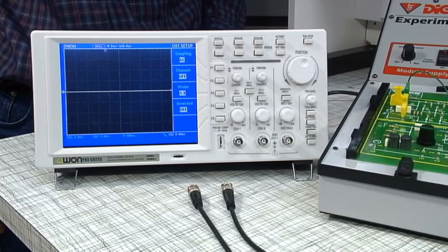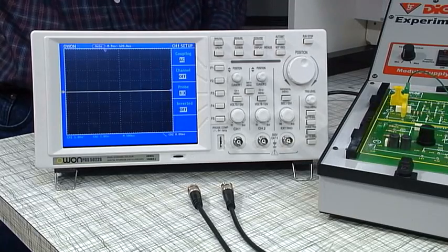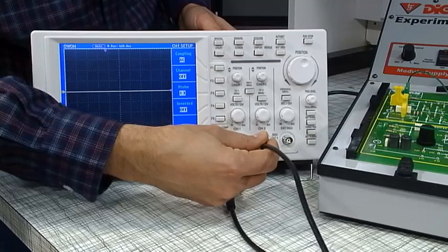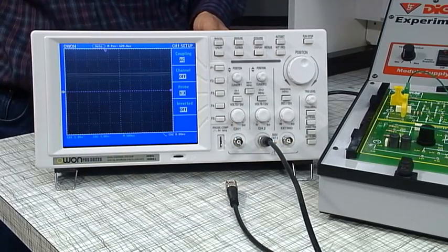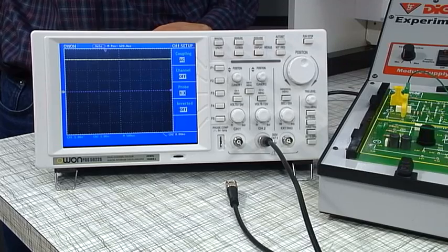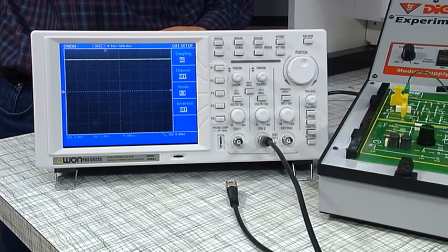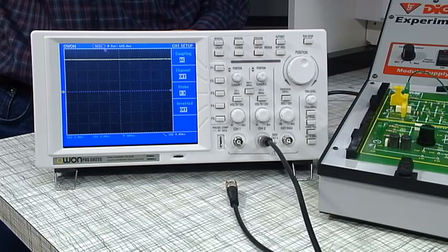Oscilloscopes can also be used to measure DC voltages. Unlike AC signals, a DC signal has no time variation. Therefore, when a DC voltage is displayed on an oscilloscope, the traced line is displayed from its reference point by the value of the voltage.